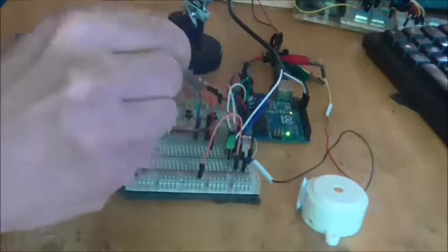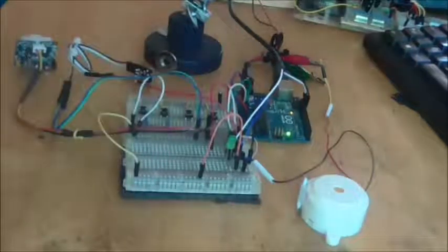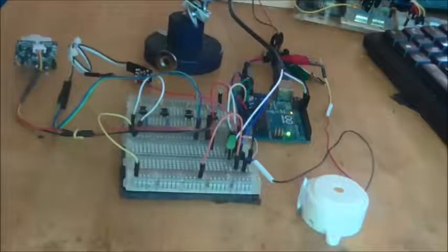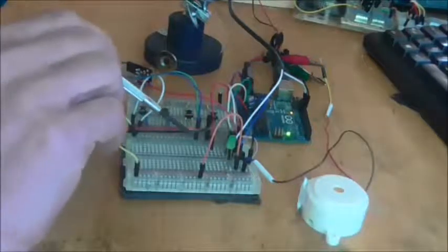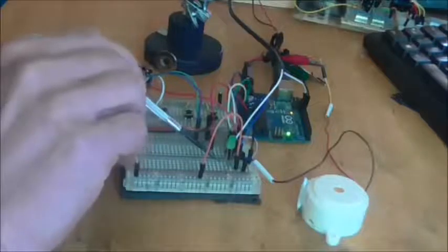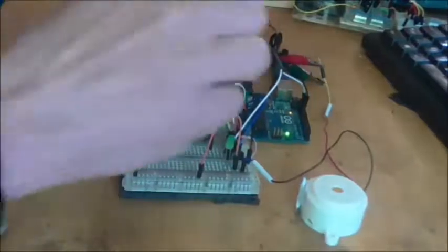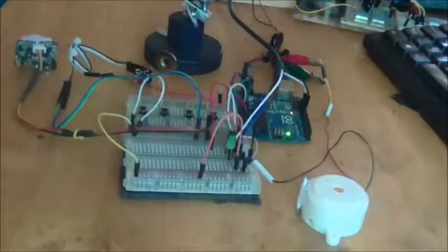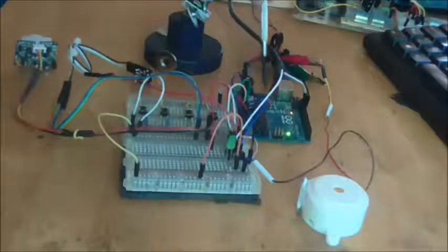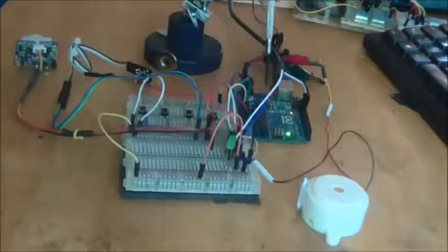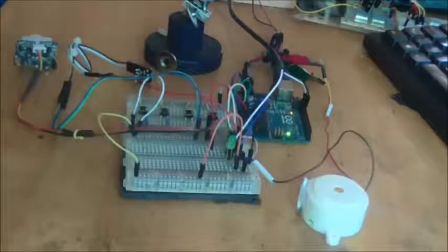So we've got 1, 2, 3, 4 pull-down resistors for each input, and a reset switch. And we've got a resistor for the LED and another one for a transistor, which is driving the siren from a 9-volt supply. The microcontroller itself is working on a 9-volt supply, but it has an on-board regulator just there, which will take it down to the 5-volt logic levels we need.